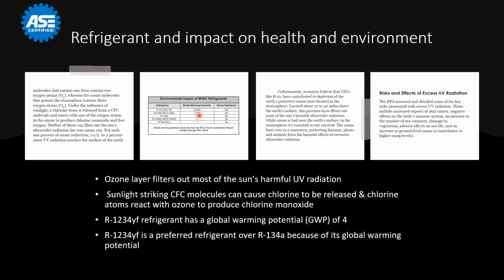Depending on who you talk to, there's a bunch of different answers out there. But regardless, the point is that our industry is still using R134A in medium and heavy duty trucks, but the automotive world and light duty trucks have all gone to R1234YF ever since 2021.